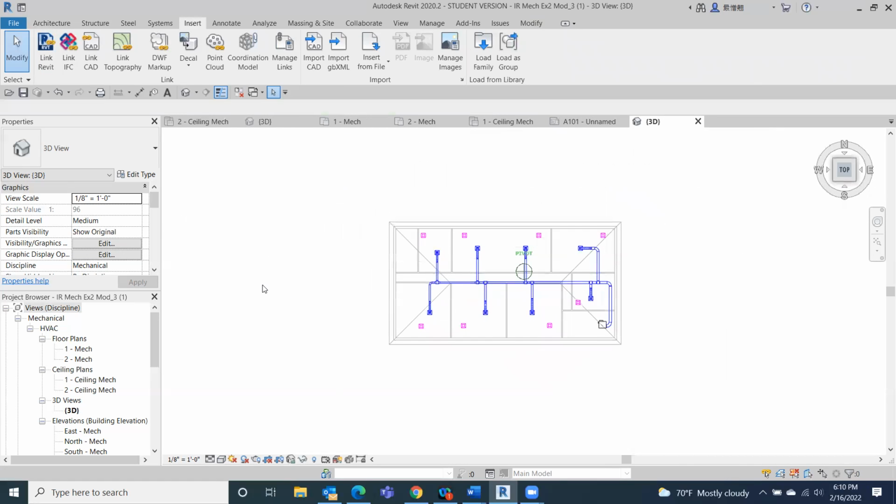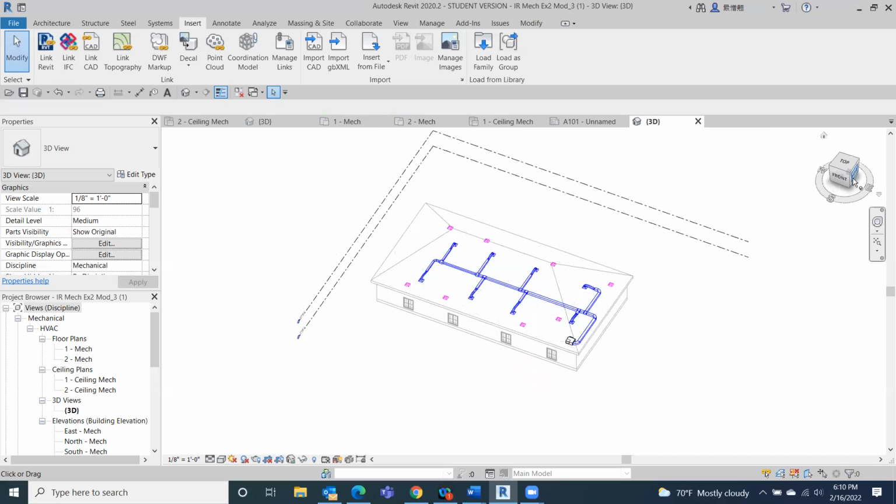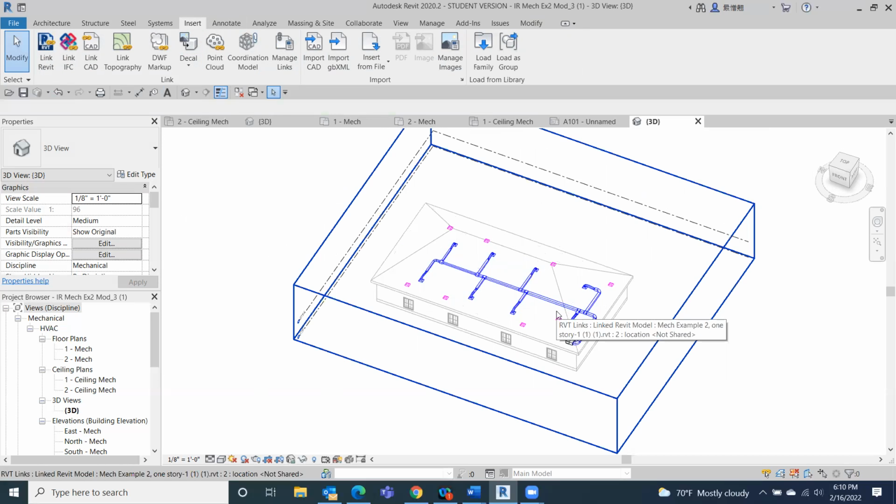If we create that mechanical drawing in there, we'll have it. And if we're importing it, we're inserting it, you're going to see these issues where it pops up, where sometimes that original one will disappear. You may have even noticed that when you close this project you needed to reinsert that Revit file. So you just go back to Insert and then Link Revit, and that'll bring you back to this situation right here.